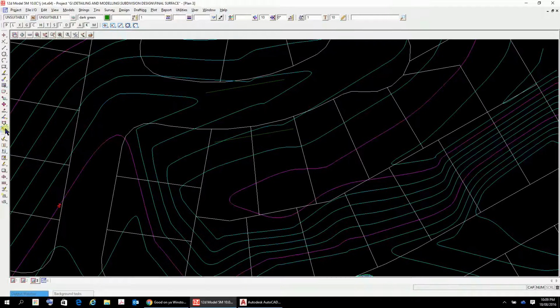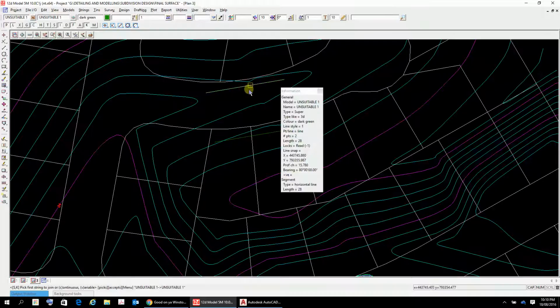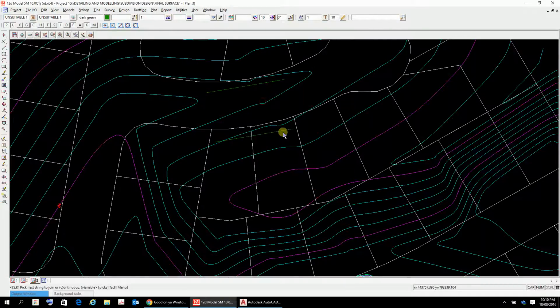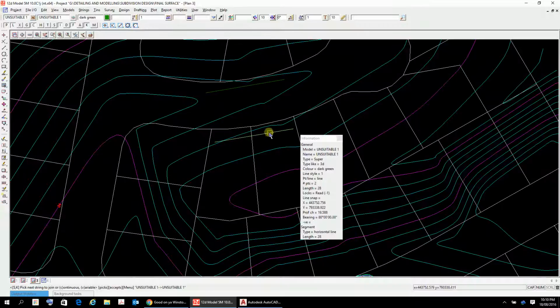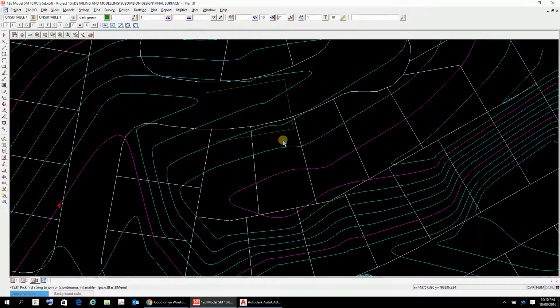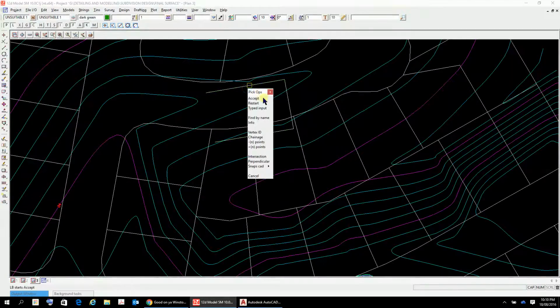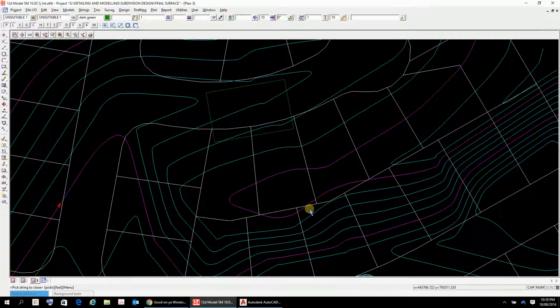So the next thing now is to just join those. Again, you just hold it there, it slips out, go to the join, there it is. So it's click, slide, accept, and then down here, click, slide, accept. Let's join that in there, and then let's just close that up, which is again here, CAD string, close, and we just accept. So that's given us our CAD string there.